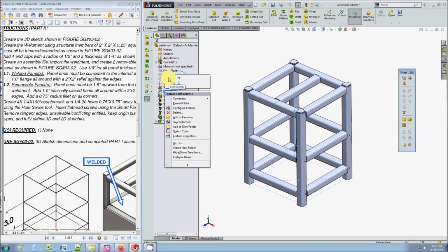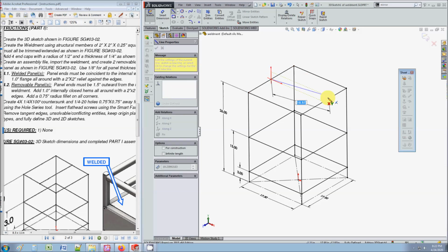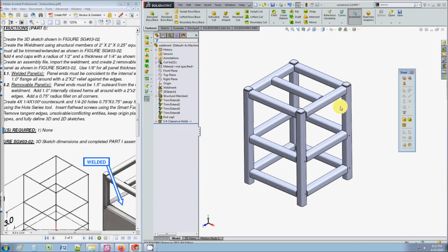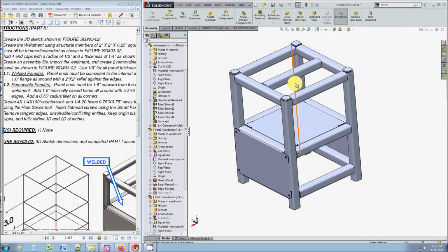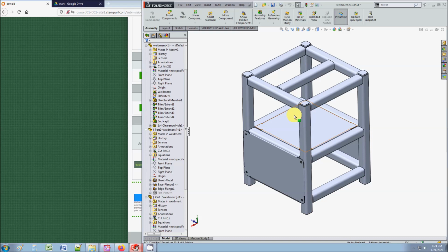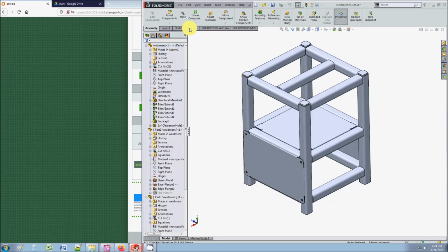That's the nice thing about top-down assembly, is that you can modify one thing and everything else updates. So let's see if we're lucky. Oh, look, no errors. We got a little lucky there. Let's go back to the assembly. Now we're in good hands. You see, now this bar matches the panel. There's no panel on the side. The panel matches the T that you see here. So we are done with the first part of this exam. So once you have this, or whatever the screenshot shows, whatever shows up here, you're ready to get the mass properties.